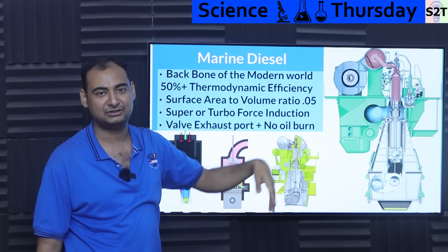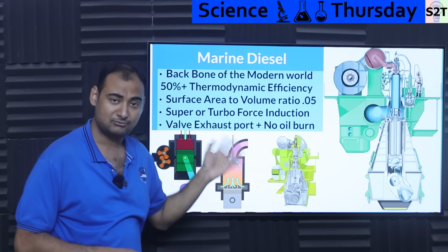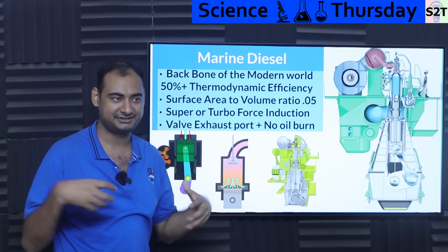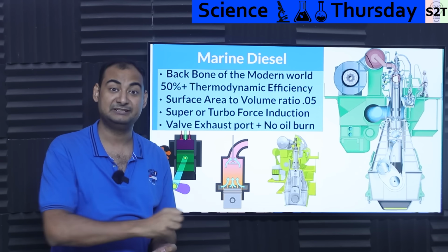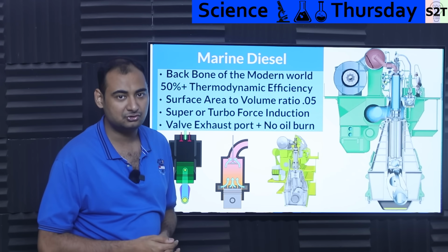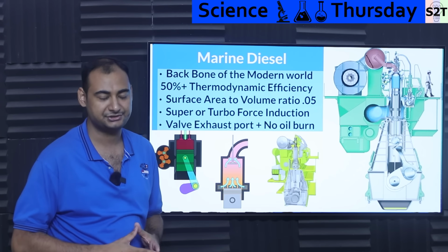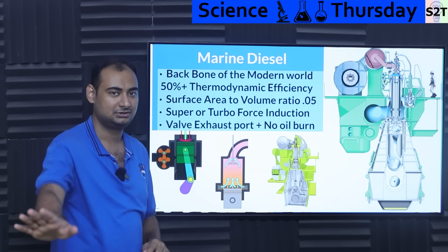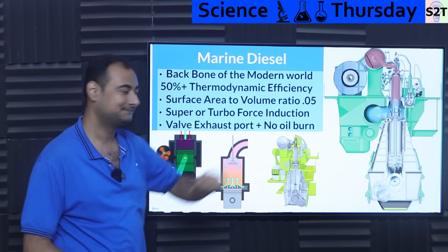So why the heck does RPM only remain at 80 to 90? Generally, turbo starts to bleed energy. Now, modern systems have a motor generator unit. So instead of venting energy, it's just like, okay, let me put load on the shaft. They can extract enough energy to shut down auxiliary generators on the ship. They will, of course, have auxiliary generators because of the regulations and all that jazz, but they can shut it off. It's like, bro, turn it off. Don't consume that fuel. Use exhaust energy.